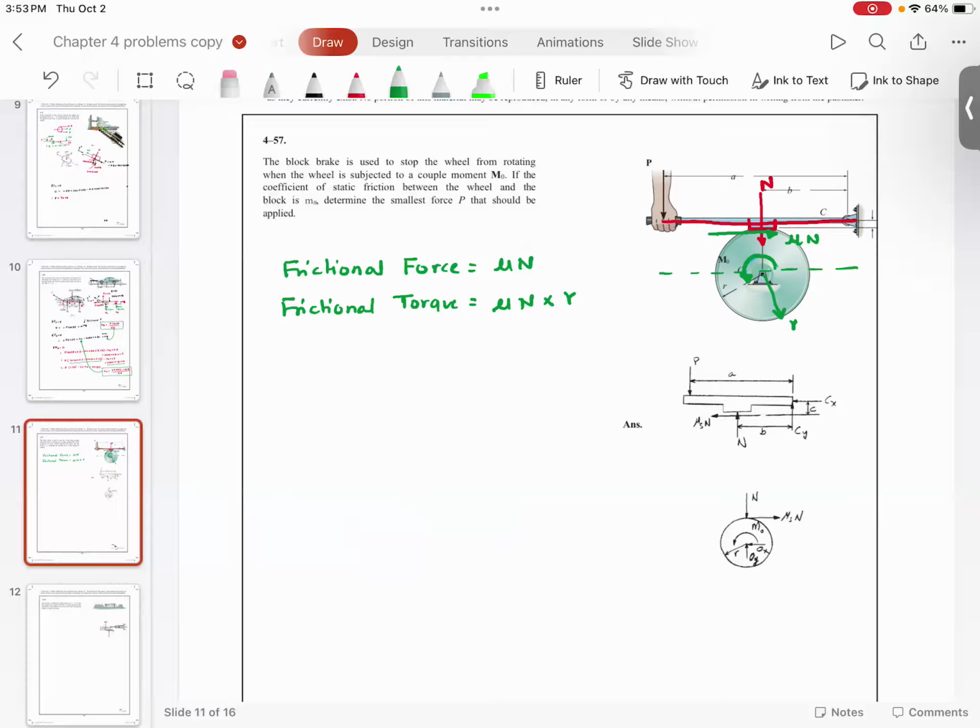I don't know. Have you seen the dyno testing on the cars or dyno testing on the wheel? If your vehicle is 1996 or before, you go for emission, they put your vehicle on a chassis dyno and basically load your vehicle and capture the emissions.